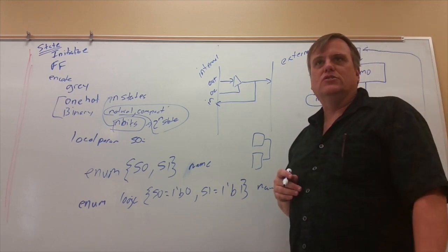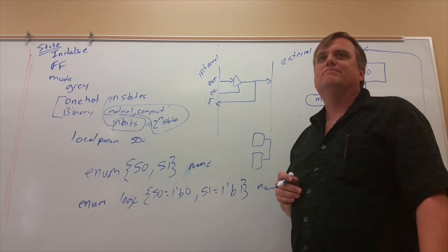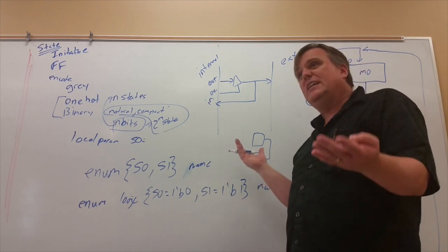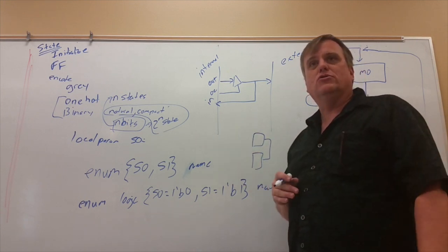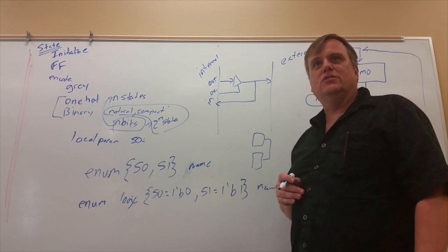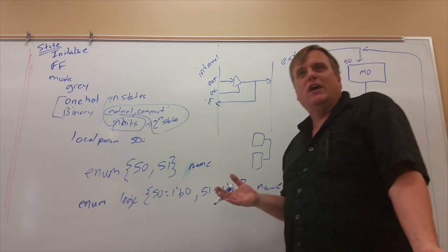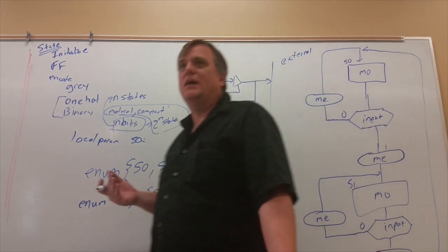Why do I want buses? We'll use it for, like, if you have multiple dies. Could I technically replace a bus by just more wires? Yeah, of course I could. Does it have any advantage? Yeah, there's no contention. You can never have contention, so you've got a stupid amount of bandwidth.